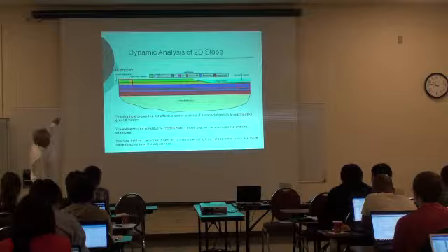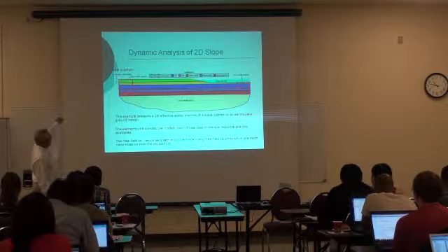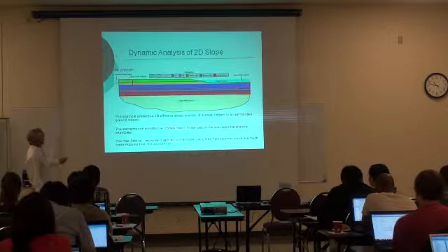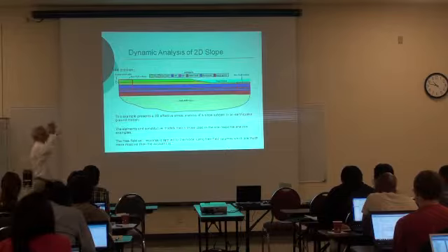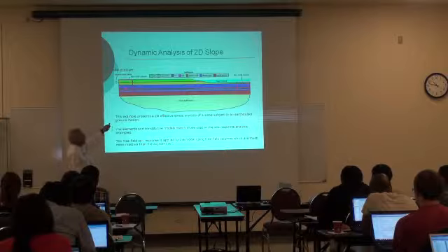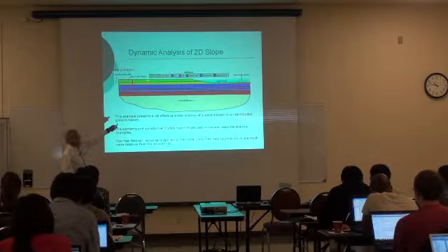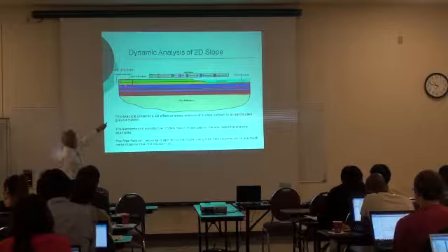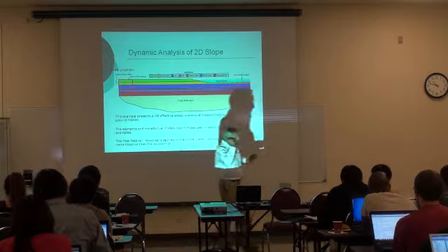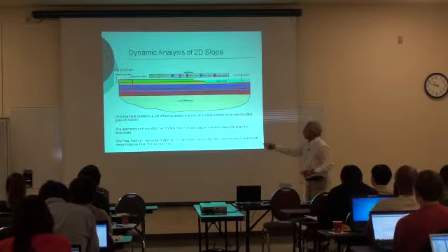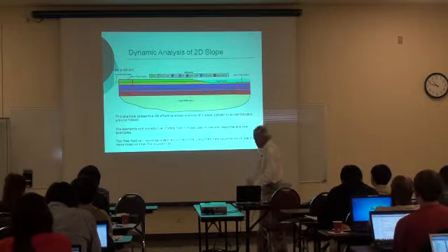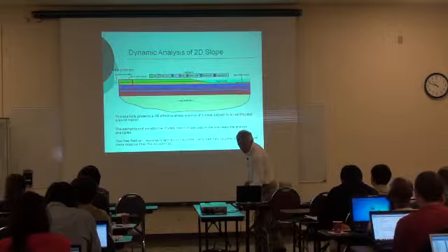Well, I model these columns, if you want. I impose the repeated boundary here, and I assume that the thickness of these columns is very high, so that the mass is large. So the mass is large here, and it's going to impose a deformation to this soil domain. So this soil domain is not going to do anything to that column because the thickness is so high that you have so much mass. Is this the best way to do that? It is one way of imposing free field response at both ends that I think works. And I describe this also in the wiki.